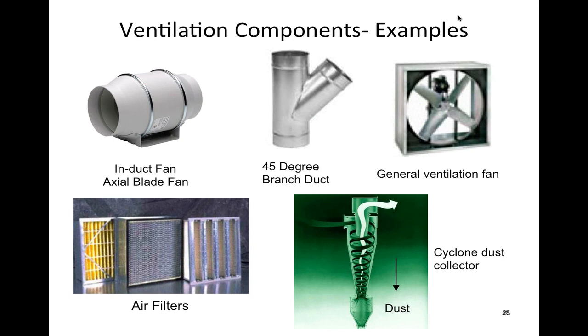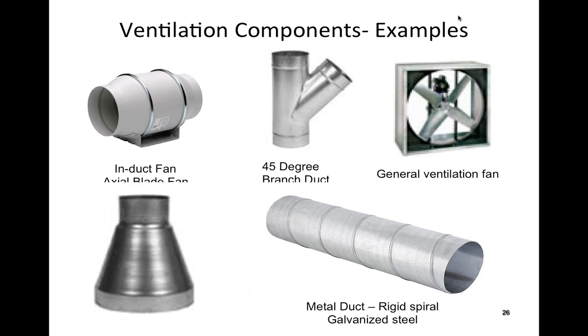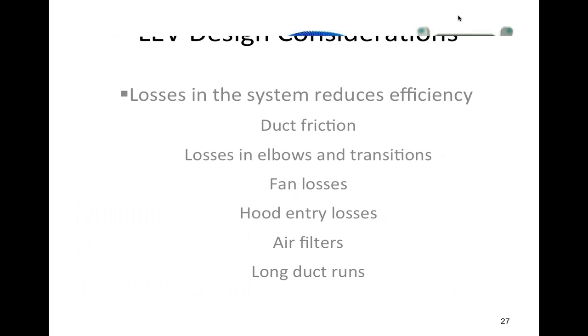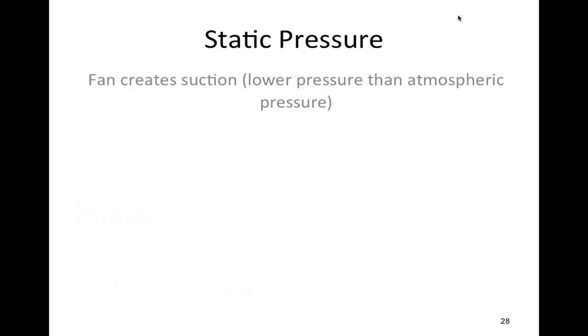It basically was a pump, a filter that you pre-weighed, and you would suck air past that filter and then reweigh that filter to see how much of that dust you picked up. Well, they use a cyclone before that filter, and that cyclone, as you pull air through it, would spin the air, and the larger particles would get caught in that cyclone and drop down to the bottom. Only the smaller particles would come through. So you could then use the same system to measure respirable particulates, particles below 4 microns, because that little cyclone was designed so that at that flow rate it would capture all the particles above 4 microns. And that's kind of what it looks like in the beginning. They actually do collect things pretty effectively.